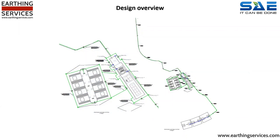The earthing system design had to comply with all relevant standards and project specifications. Due to a combination of a high 1-phase earth fault and a high resistivity soil model, an extensive earth is required to ensure the site is classified as a cold site. A cold site relates to a rise of earth potential, ROEP, of less than 430 volts. Anything exceeding this would be considered a hot site, which may require additional steps relating to separating HV and LV earthing provisions. The earth system comprised a series of horizontal and vertical electrodes.